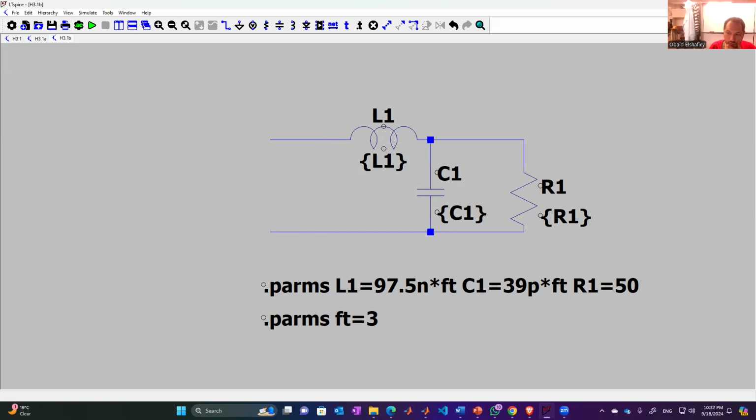Right now, we need to plot a Z equivalent. Z equivalent is the Z looking through the circuit. So how can we plot this? We should know that Z is equal to V over I. So if we set a source of 1, let's say I is equal to 1, so Z will be equal to V. That's like a smart trick.